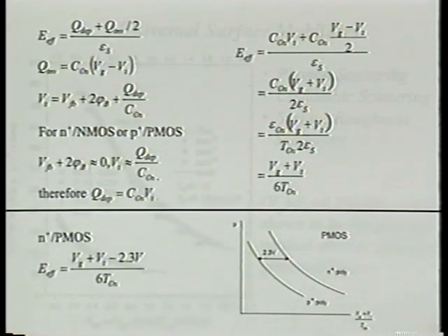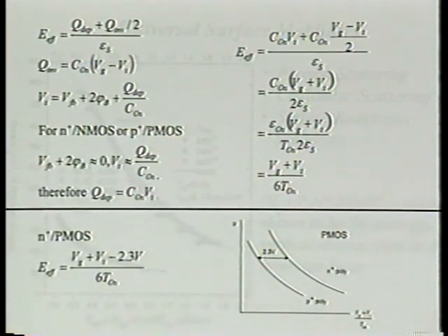Okay. So that is a very useful model to relate the mobility to this one quantity called E effective. The only problem with that is that E effective, although if you sit down and try to calculate it, it's not that difficult, in practice is rather elusive. I'll give you some examples.